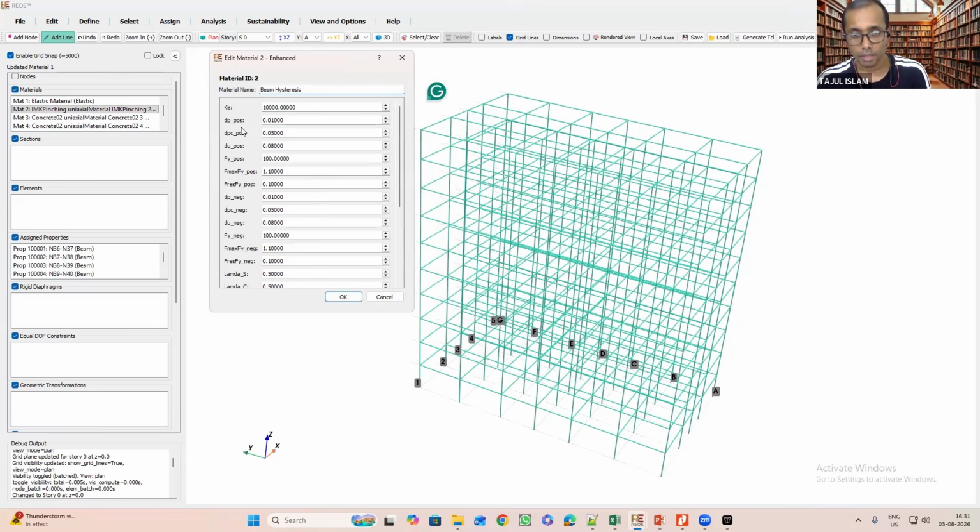And now here these parameters come from the calibration. Okay. Normally, if you are familiar with ETABS, these values come from the ASCE 41 curves. Okay, there is a code ASCE 41 for nonlinear analysis. So these modeling parameters, backbone curve modeling parameters, are governed by ASCE 41. But here we have not yet implemented ASCE 41, so you have to calibrate these values yourself and assign. Okay. Now, since we do not have calibrated values, based on my experience with my research, I am defining some values. Here it is 1.5 into 10 to the power 10 stiffness.